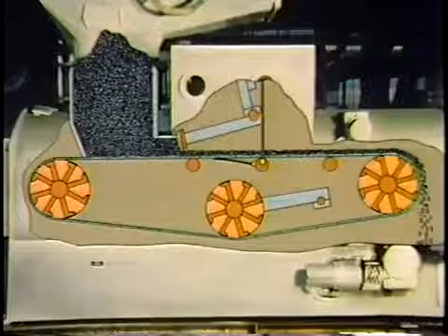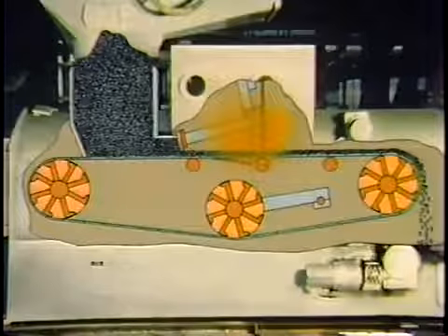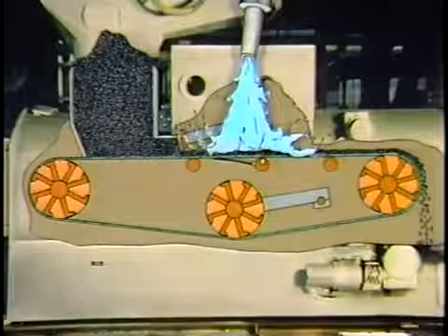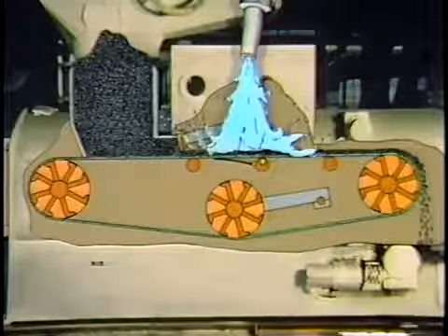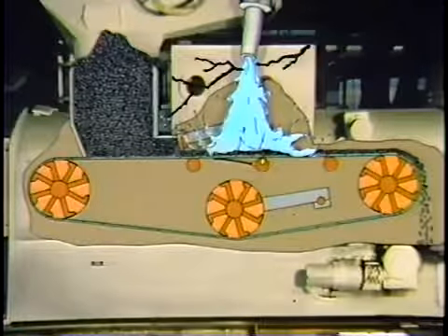Another thing you want to avoid is flooding the burning equipment with water. Bunkers, feeders, pulverizers, and air preheaters are all made of heavy metal. If a fire occurs, the temperature of the metal increases. If water is suddenly poured on the metal, it will cause the metal to cool rapidly, and this can create warping and cracking that will actually damage the equipment more than the fire could.